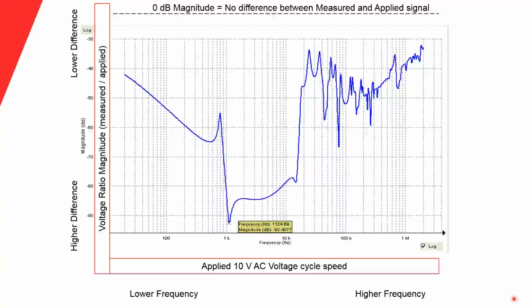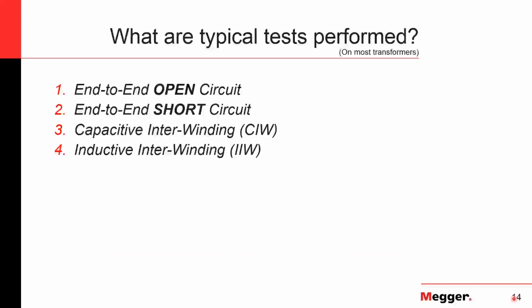And then, as I said previously, at the low frequencies, you're looking more at core. Mid-range frequencies, you're looking at winding. And then as you get into the high frequencies, this is more your taps and connections.